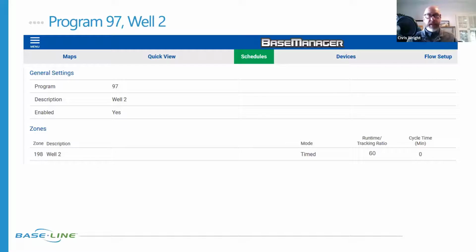So we had a customer or a participant ask the question, why would you not recharge the tank based on level pressure in the tank? Lower level pressure, more wells come online. So again, we could have done it with pressure using our pressure technology, but in this case, we were conforming to what they had spec'd in terms of the cistern and the pump station, correct?